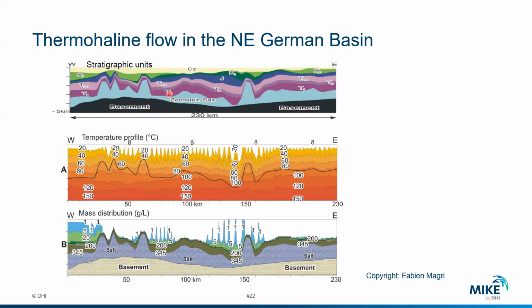And then what you see here is that there are some significant salts, which will play a role in the geothermal system. So you have heights, temperature profiles combined with salts. So you need to solve both equations, flow, obviously mass and heat. Then there will be a density depending on the concentration, but also depending on the temperature. And these types of problems are called thermohaline simulations. So if you are interested in those, there are a number of papers that you can find where FEFLOW was used for those applications.